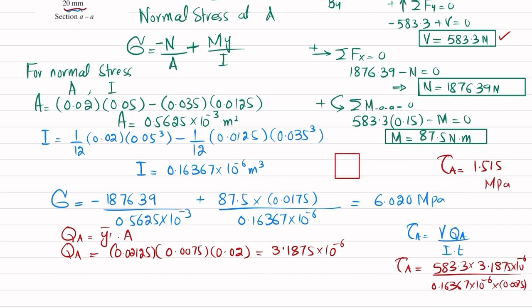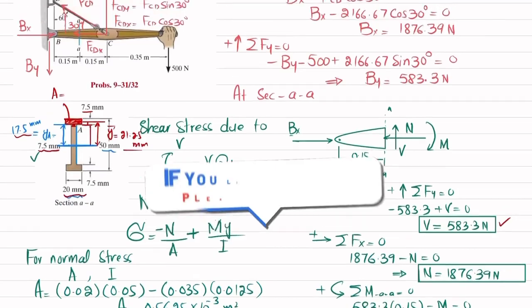Now if you draw it on an element, so this is the element. So normal stress at point A, which is sigma x, is this one in the x direction. This is sigma A, or you can also write it sigma x. So this is sigma x, and there is no sigma y because there is no stress in the y direction, and shear stress will be like this. This is tau xy, or that is tau A. This is tau xy. Clear? Now this problem is ready to solve.